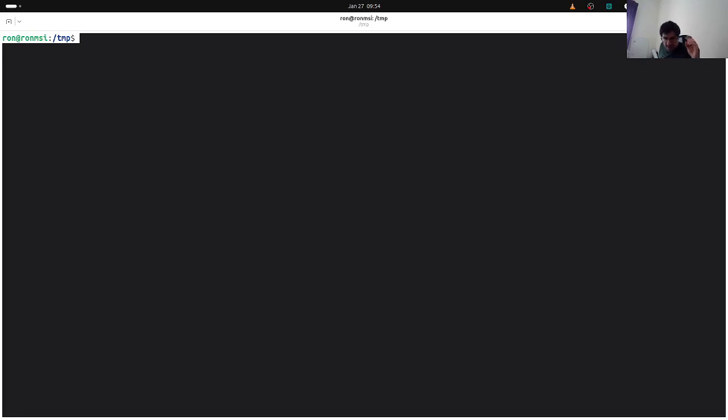And one last thing, I think I said it in the summary, but I showed the difference between having the TF card and the debug cards, and when they kick in. So you will not see this boot loop that will tell you, hey, this device is alive, or hey, I recognize an SD card, I don't recognize an SD card, there are all kinds of statuses there. If you don't connect the TF card, and if you connect the USB debug port, then the SD card will not load. It's very, very important. But if you connect the USB debug port, you can actually load an image over there.